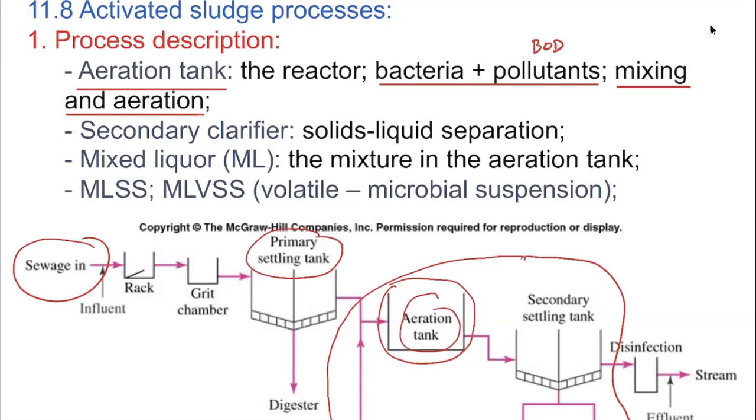We bubble a lot of air from the bottom, right? We introduce a lot of oxygen here. So we can also imagine that the bacteria are enjoying their unlimited food, right? We're introducing a high concentration of organics. We also give it an unlimited amount of oxygen, so it always has enough oxygen there.